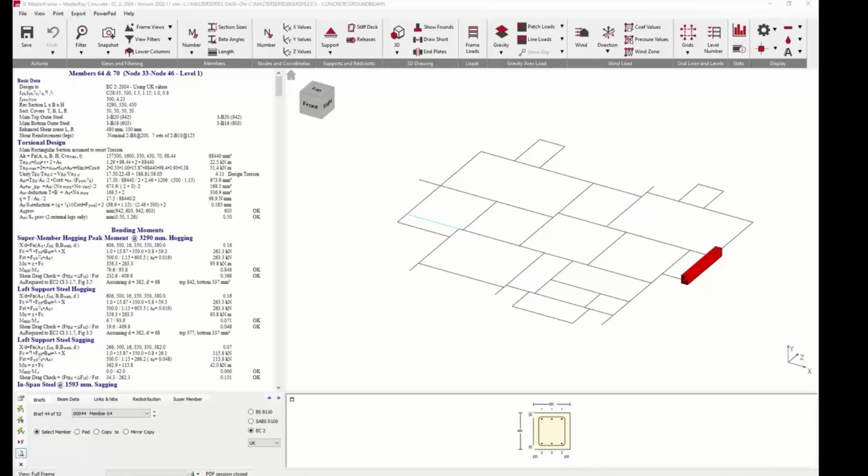Can you have a wide beam? The load from walls may be eccentric. Well, yes, you can add in wide beams. In FE, it's not really a problem. The load is just applied where it's at. In beams, you can, in the loading component, apply them offset, and you'd have to apply them as member loads and offset them. Why do you have a support width of 200 with beams 350?